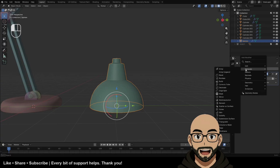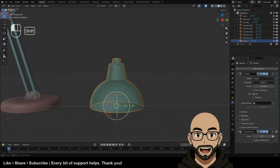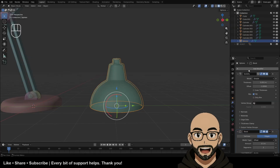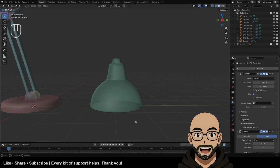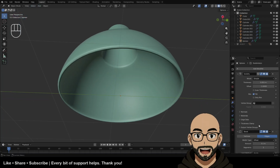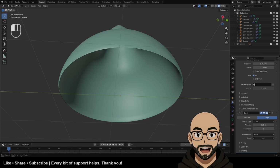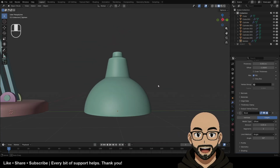Now we can apply some modifiers to this, just to generate, solidify. So we can add some thickness, as you can see. With the X-ray on, you can see how thick this is. And then what we're going to do is add a bevel, so we can round these edges off. And let's just add a subdivision surface just to smoothen everything out again. Let's turn this off. And you can kind of play around with this bevel and the angles. See what works. I'll leave this at 30. So 30 seems okay.